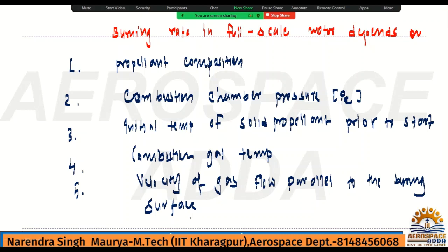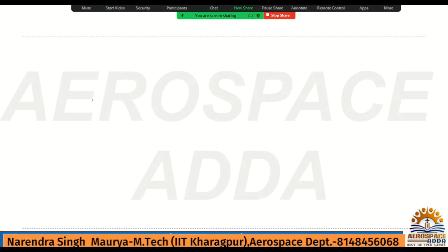So this final formula I am just going to give you. This is very important. At any given initial temperature, remember, temperature is constant for this. When they did the multiple experiments, they kept the initial temperature constant and only changed the combustion chamber pressure, and for different combustion chamber pressures they got different burning rates. So they developed one relation, okay? That's the meaning of it.